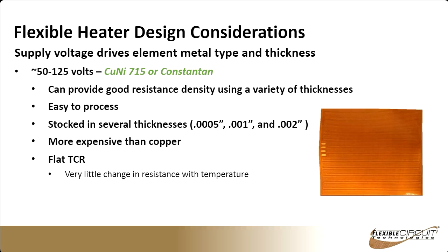Okay, and then the second one is, how do we calculate the resistance? We have a resistance calculator that we use. We have CAD software where we can figure out how many linear inches we're going to have on our traces. We put it into our calculator and that'll spit out the trace width that we need. We like about a 50% coverage, 50% trace and 50% space, and we can vary from that depending on the watt density.